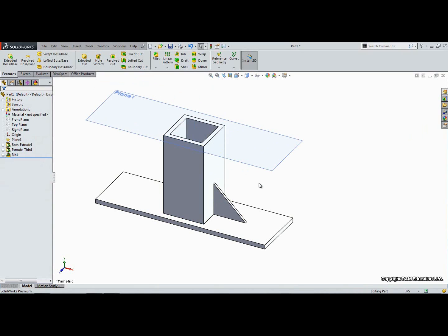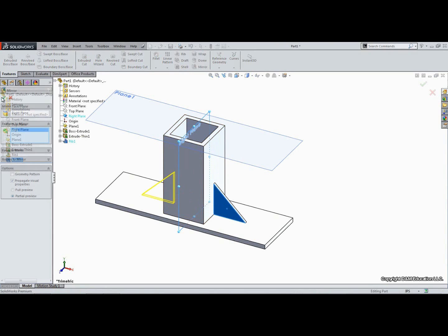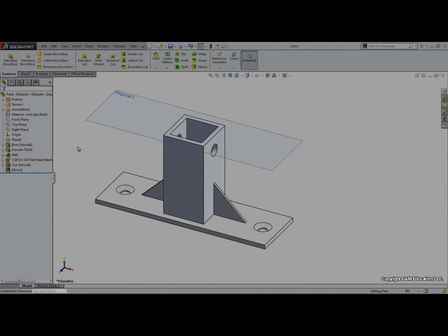It is important to make sure that the design intent is kept within the model. This means to create the model with the mindset that if one were to change dimensions on the model, the basic end geometry would still be the same. When possible, and if it makes sense, use symmetry. Model objects symmetrically about the origin, as can be seen in this part.